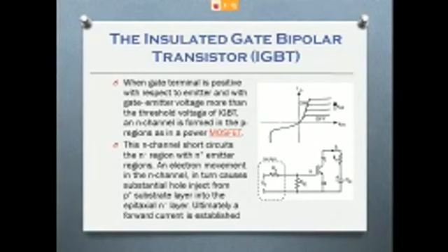So without discussing all these lines written, I'll just directly go to the figure. The VCC on the right end we can consider as a battery, and the RD, or load resistance, would be just a bulb or an LED light connected. Just think the collector and the emitter is where the switch had been, like where the transistor is now. Let's take that away and connect a switch there. If I short the collector and the emitter, the current would pass, the circuit would be closed, and the light would blink. So in that place where the switch had been, we are connecting an IGBT.